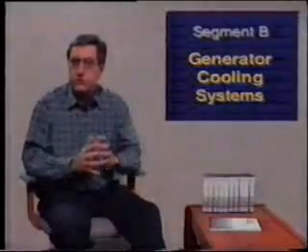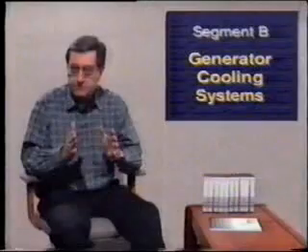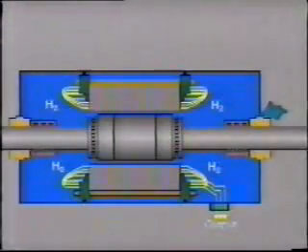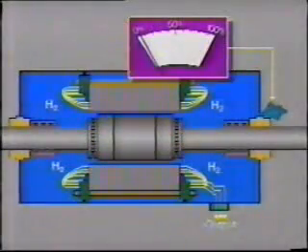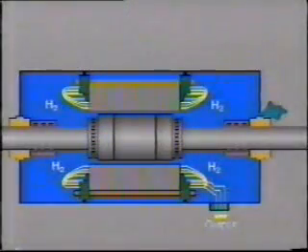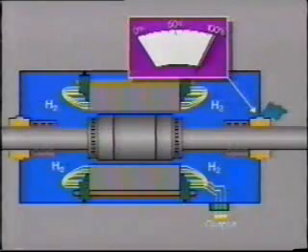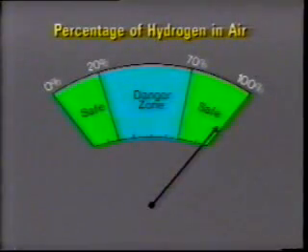Are there any dangers involved in handling hydrogen? Well, the answer is yes and no. For example, a small leakage of hydrogen into atmosphere presents no danger at all, as the hydrogen is completely diluted by the large quantity of air surrounding it. Also, at the other end of the spectrum, pure hydrogen cannot ignite and so presents no danger. However, certain mixtures of hydrogen and air do present an explosive mixture.